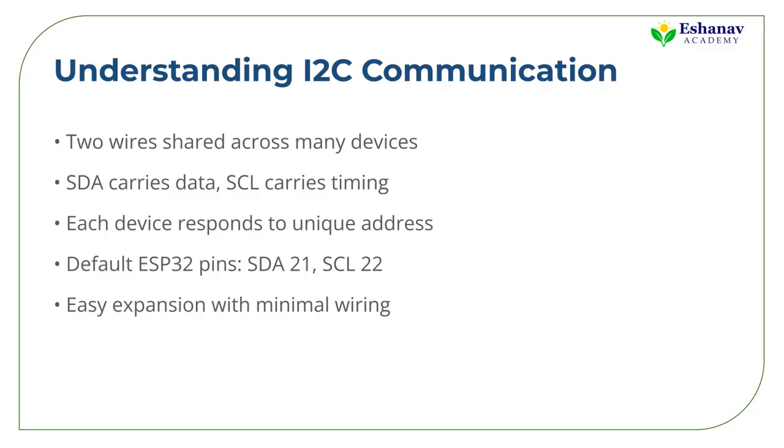The beauty of I2C is its simplicity. No matter how many devices you add, those 2 wires don't change. The catch? All devices share the bus, so speed is limited, but for most sensors and small screens, it's more than enough.